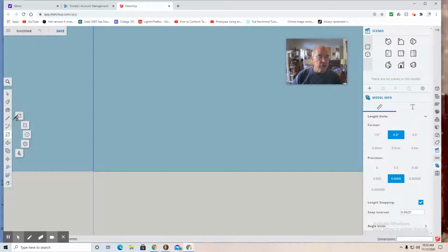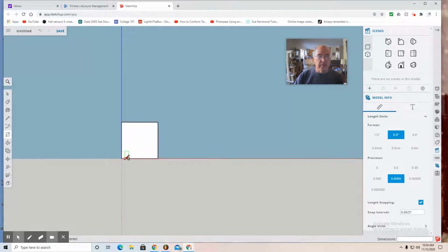I thought I'd just use a rectangle to start, and the blocks that we've created, as you remember, are 1.5. So I'm going to just make a block here and then move up. So now I have a cube, and I'm just going to take my hands off the mouse and go 1.5, comma, 1.5. And you can also verify down in the bottom right corner where you see dimensions. If it shows 1.5 comma 1.5, you're entering those inches. So then you hit the enter key, and don't get alarmed if it gets small. You want to just use your mouse wheel to zoom in.